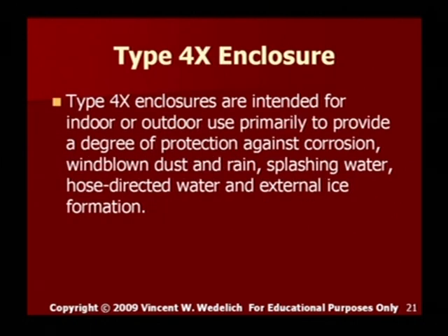The 4X enclosure is identical to the type 4 enclosure, except the X is for corrosion resistant. What this means is it's made out of something like stainless steel or some types of plastics. This is a very common enclosure on an offshore job. Very expensive. These are NEMA 4X stainless steel 316 or 304 enclosures.